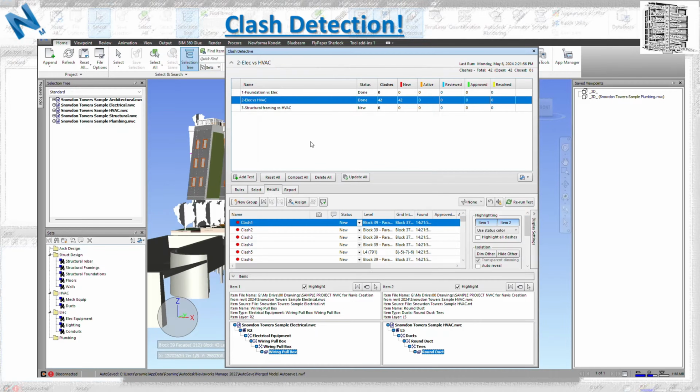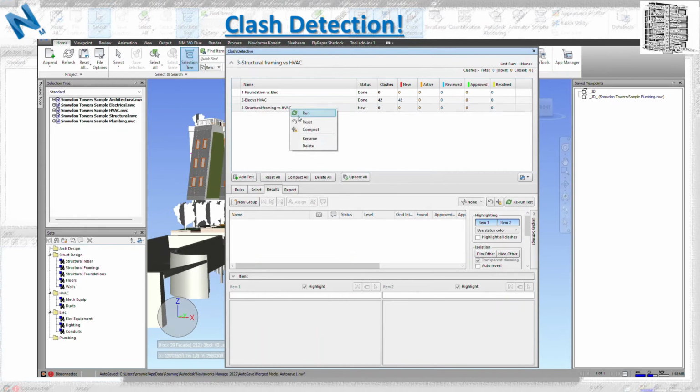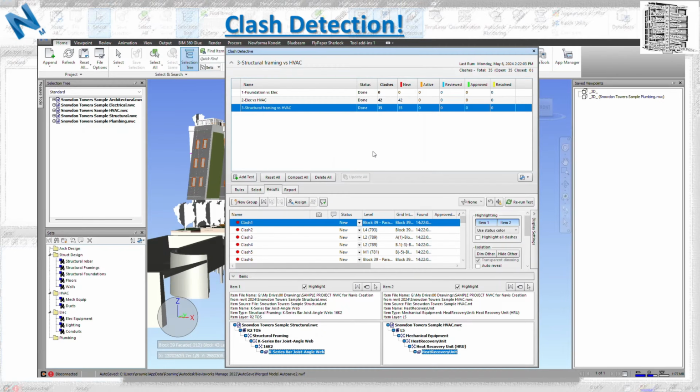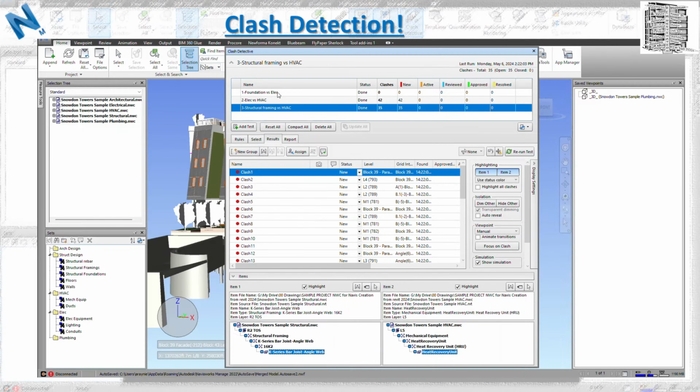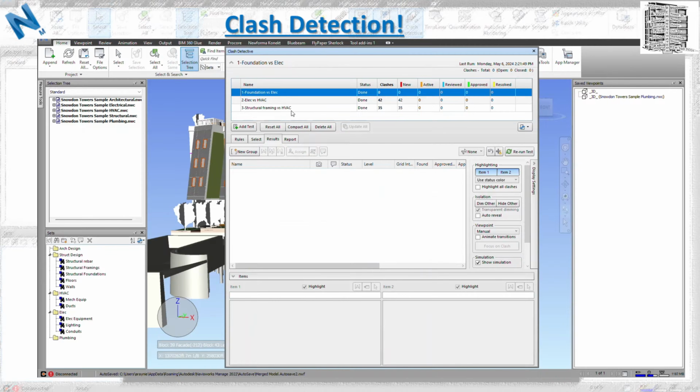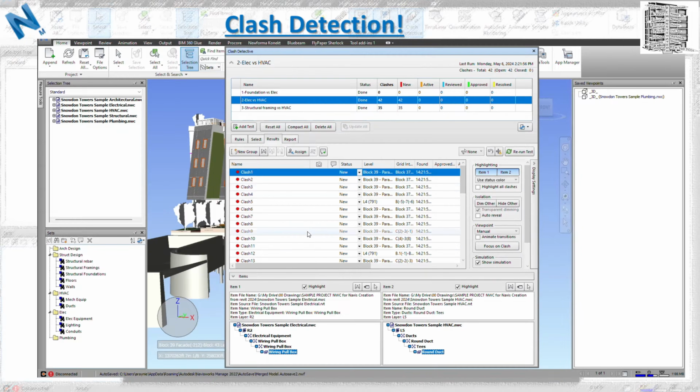Okay, right now I have 42 clashes as new because it's the first time. All of them are going to be red, and the next time when I update, it turns all of them to orange, which means they are active, but they're not new. It means they've been there for a period of time. So right here, nothing, it's fine. Okay, we move to the next clash.